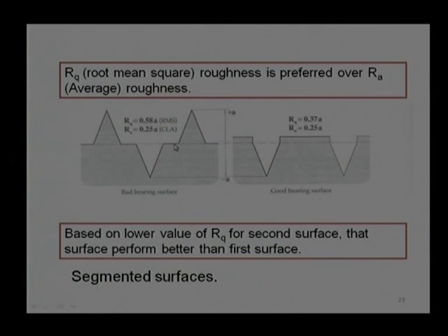In this case, if only a straight surface or plane surface is there, the effective area of heat dissipation will be lesser compared to the heat dissipation area available on this surface. So, this kind of segmented surface, this kind of punch surface or nodulate surface will be preferred over an irregular surface.